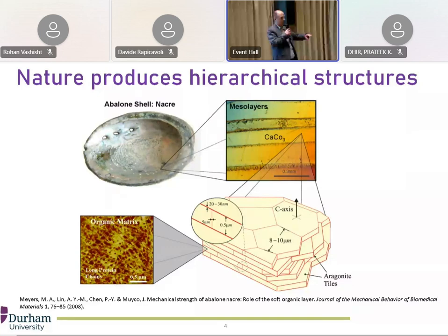So you drive the crack into soft space and extend the surface of the cracks, and more energy is dissipated. So it doesn't crack like glass, but more like a car windshield when it cracks everywhere. It's a distributed cracking, and that requires more energy.